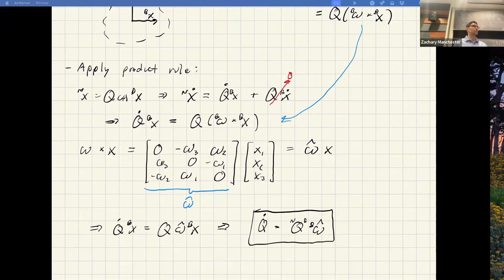Make sense? Everyone, yeah. Can you just turn that into omega hat n? Yeah, you totally can. What would you do? I mean, is it q and b times omega hat b, just omega hat n? No. Well, literally you just hit it with another rotation matrix and rotate it back. It turns out what happens here is if you transpose the entire thing, it ends up being q dot for the n to b rotation equals omega hat in the n frame times q and b.